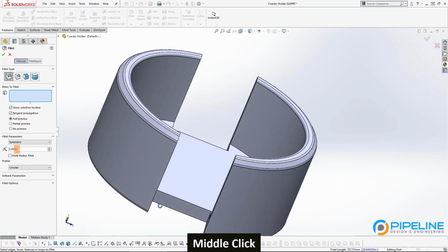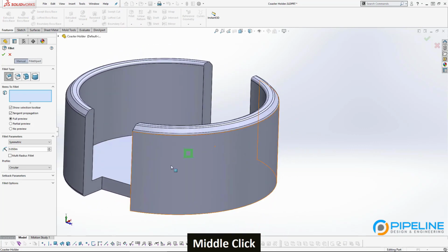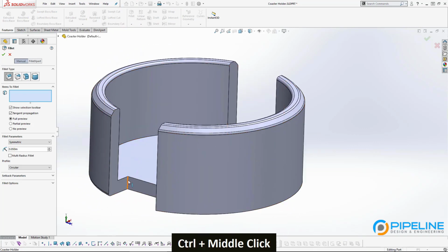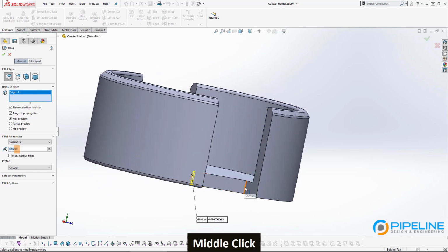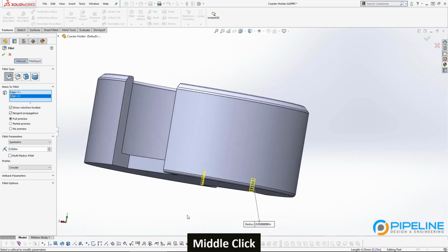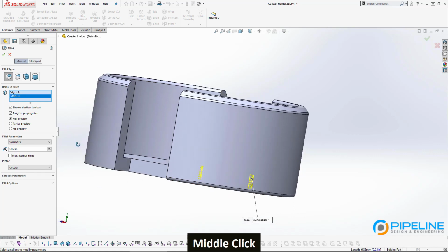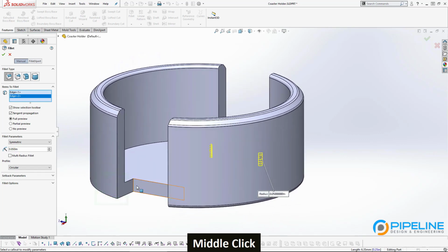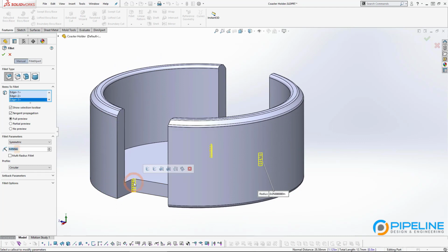This is a pretty abrupt feature here. For machining, if this was going to be a machine, this would need a fillet, but it's also just kind of ugly. So we'll talk more about machining in the future, but for now, I'll just select these lines. Now, one thing I can show you is a somewhat new feature in SolidWorks, added in the last 5 years. If you select a line and let go, there are some options here where SolidWorks is going to guess what other lines you could potentially select. And a lot of them are not very useful usually, but some of them will be useful.